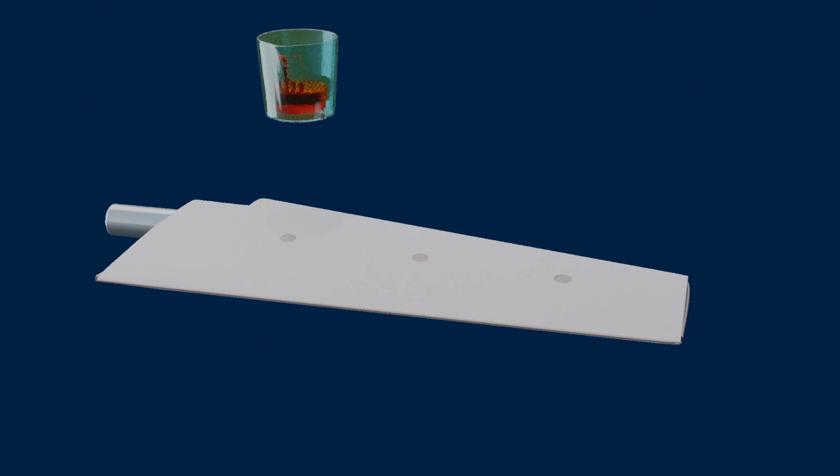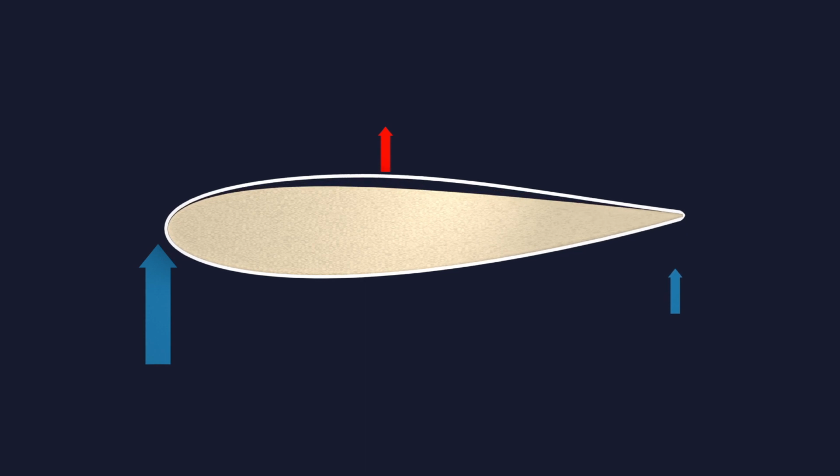The fundamental problem with this design is that lateral forces are transferred to the shaft only through the foam. This works well under compression, but it's a poor choice under tension. Unfortunately, when turning to the right, the starboard side of the skin is put under compression, and due to the curvature of the foil, this results in the production of transversal forces pulling the skin away from the foam core.